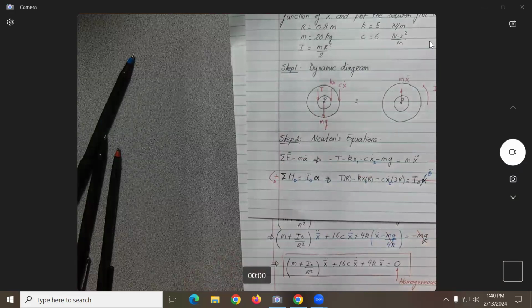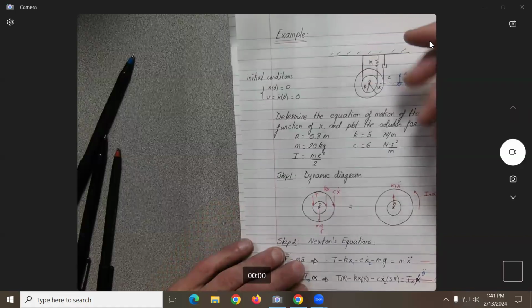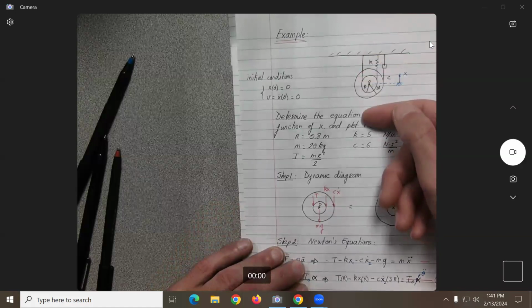Correct, but then what is the assumption that we're making? That we are writing the equation of motion from the equilibrium position. Yes? You understand that part? Because if you say that you write it from the equilibrium position, that means the spring and the damper are already stretched, no? And you write it from that location.